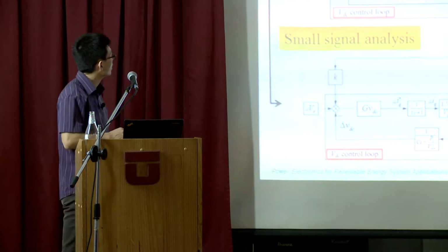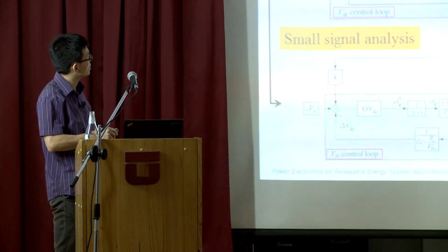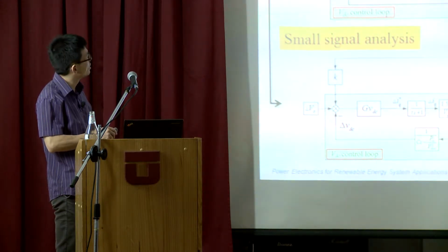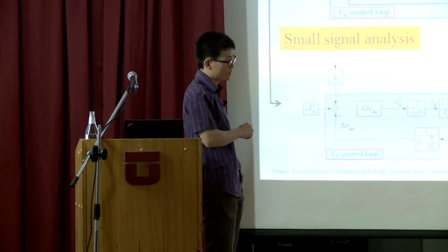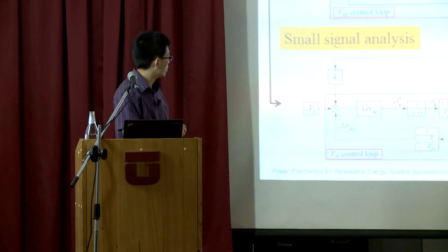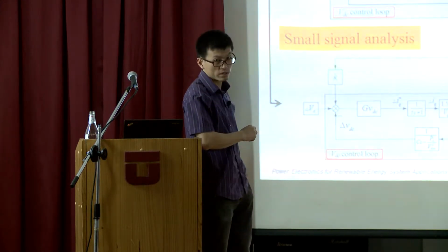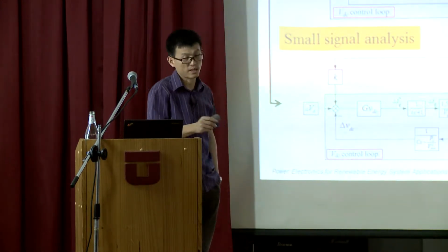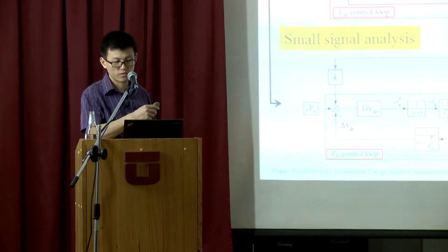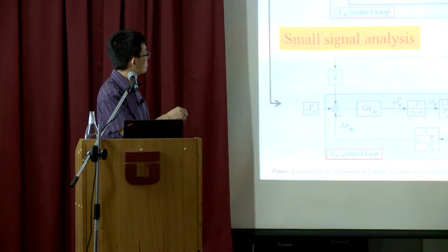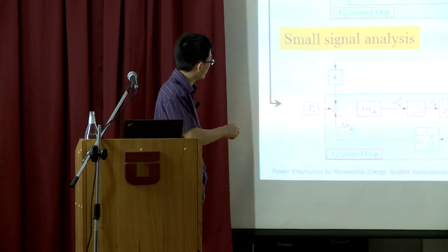Okay. And then the droop itself, you see the droop itself comes from the current I/O at the feed forward K into this loop to the current point here. If you are very familiar with control theory, this is more like feed forward control, and this should have no impact on the dynamics of the system. Again, we do the similar transform. You do small signal analysis, and you find out, similarly here.